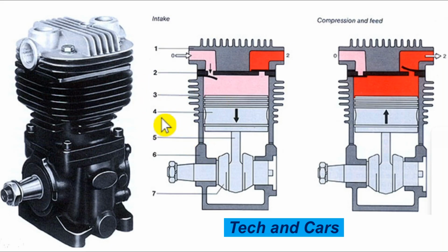Now, what are some of the troubles that are associated with this air compressor? Well, it could be, for example, a slow air pressure buildup. This is one trouble. If the gauge rises slowly, if it is not rising sharply, then that indicates some sort of air leaking, for example. The most common cause is air leakage.